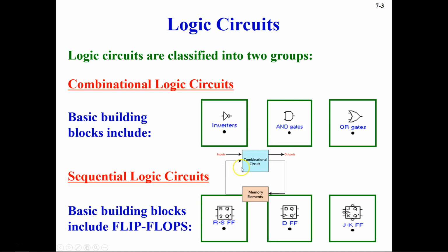And you can see here, this is the block diagram of a sequential logic circuit where you have a combinational logic circuit here, and then you have a memory element here. In this memory, the past output will be stored, the output which is coming from here, and that will be called your past output, and that will be sent through this feedback, stored in the memory element, and then fed back to the input here. And when they come here, then they will be called your past inputs. Now here the memory, you see, is nothing but the flip-flop.